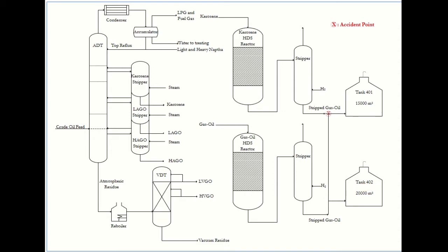So what is the HDS unit? Basically, the HDS unit, known as the hydrogen catalytic desulfurizing unit, is a unit to remove the sulfur compounds from the product. For example, sulfur compounds from middle distillate such as gas oil can be removed to achieve the blending qualities for the diesel fuels and the light heating oil. This HDS unit is also coupled with a stripper column respectively.